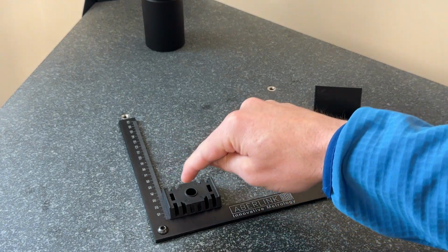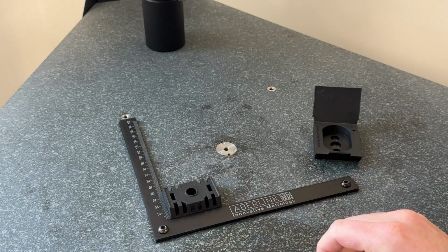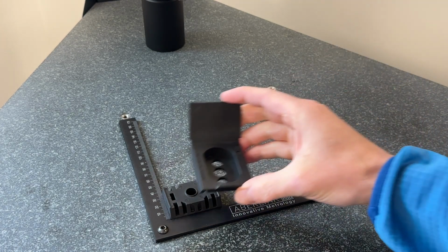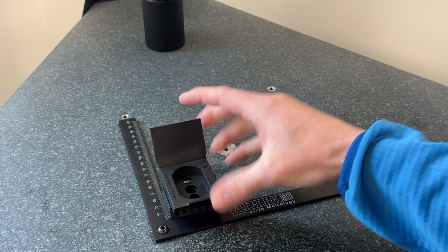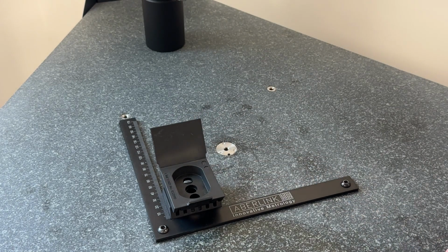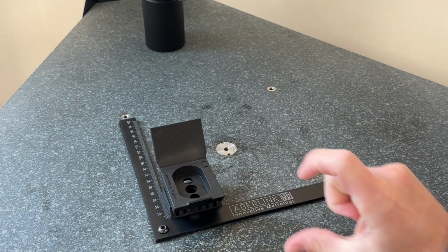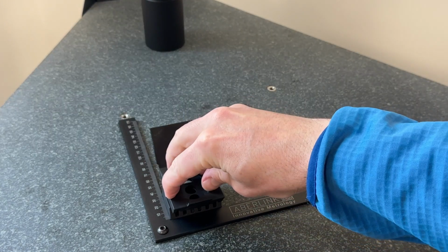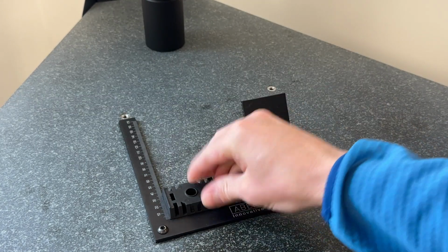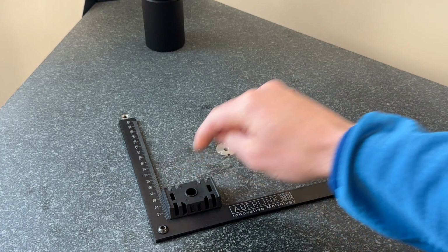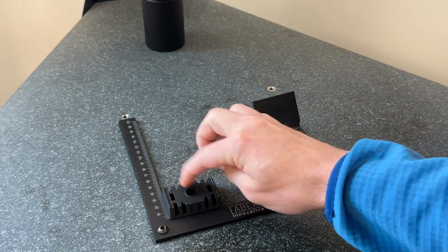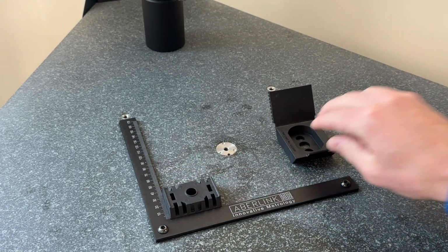So you can imagine the initial program is going to be the single bottom mating part. We'll reference off the granite, the center hole and the side face. Then we need to insert a pause so that we can then assemble this ourselves, click it into place as it would in the real world, and measure the top face. This will give us the overall height as a combined measurement rather than guesswork between individual measurements where we can only take a handful of points on both surfaces.